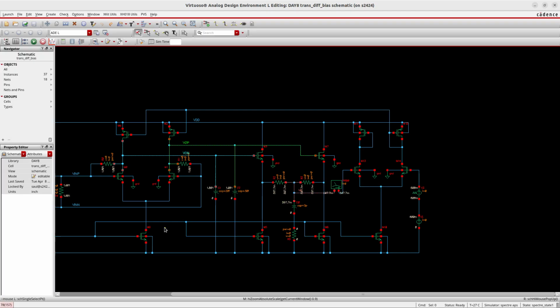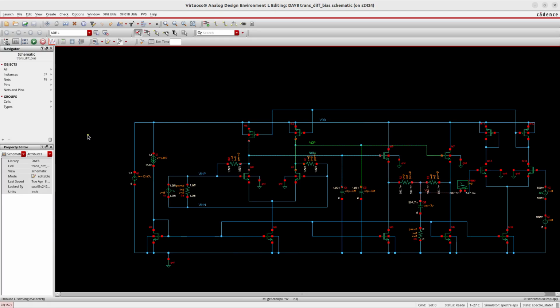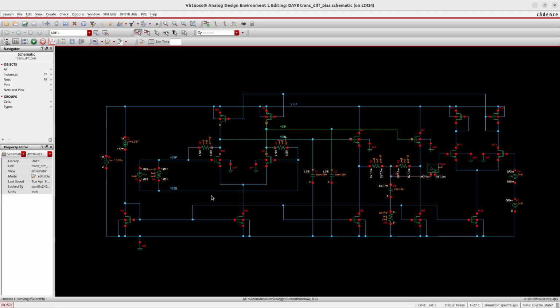In a more complicated amplifier, for instance, a 2-stage amplifier, or using a cascode, there will be much more gain. So we definitely don't want to add more gain in the correction amplifier. We just need to do the comparison and then set the right currents at the amplifier. Okay, so with this example of a differential amplifier, we finished the class on biasing.